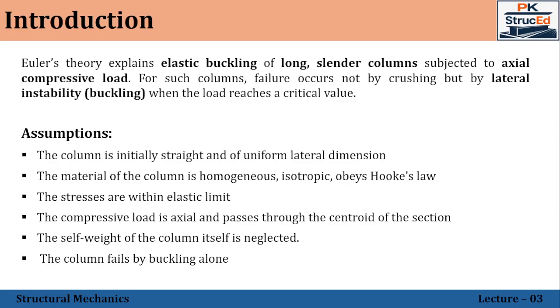Let us begin with the basic idea. When a short column is subjected to axial compression, it fails due to crushing of material. But when a long, slender column is subjected to compression, it does not fail by crushing. Instead, it suddenly bends sideways and collapses. This phenomenon is called buckling.